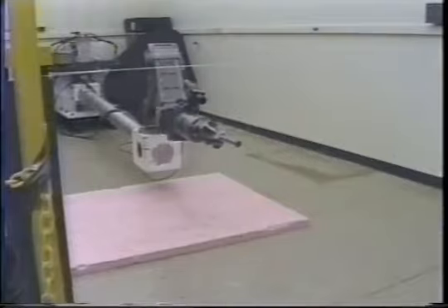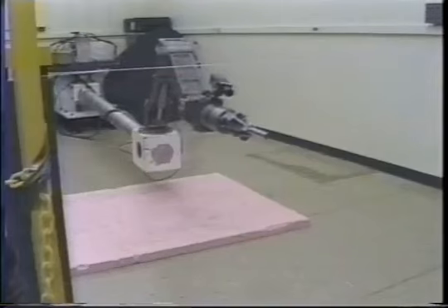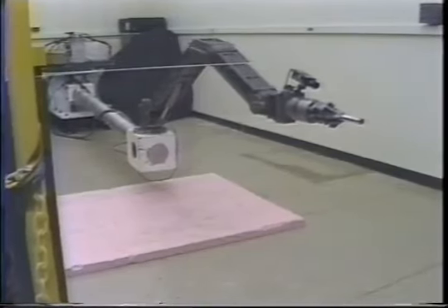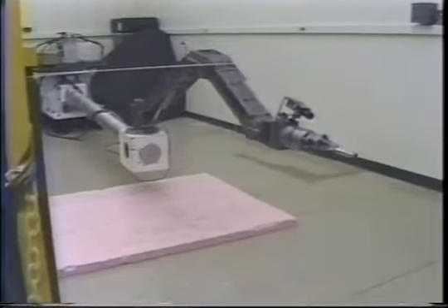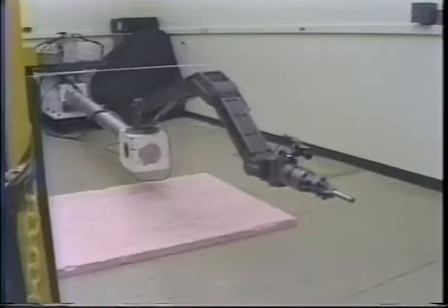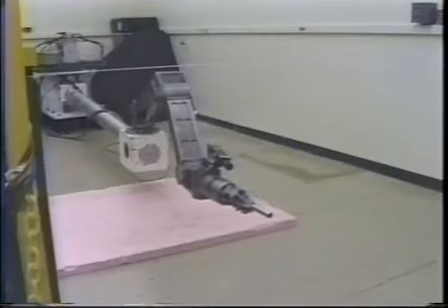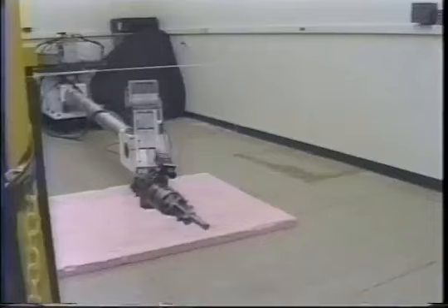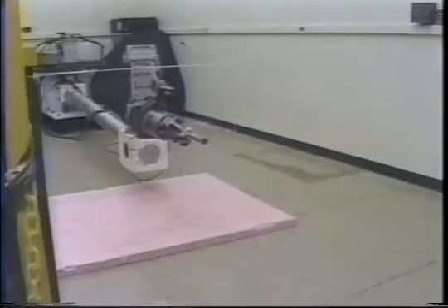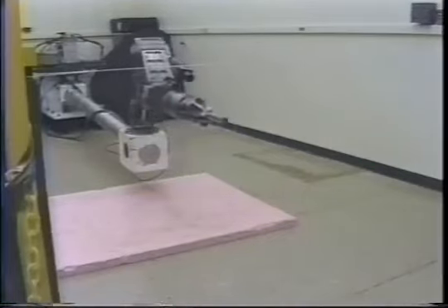Using an industrial manipulator testbed, the vibration and contact control of a flexible manipulator is demonstrated. With the proposed control, the micro-macro manipulator will be able to perform a fine motion in a large workspace accurately, efficiently, and safely.